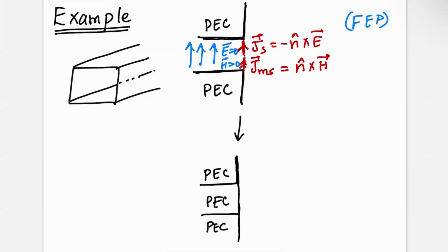Okay, but when I put a PEC, now all of this is PEC. And so I can erase this. All of this is PEC. Okay, and I had some currents over there. What happens to the currents, right? When I had the currents and then I put a PEC, which means that the currents were in fact impressed on this problem, right? They're not induced from the PEC, they existed already, and then I put PEC there. So then the currents would have images, right, from image theory.